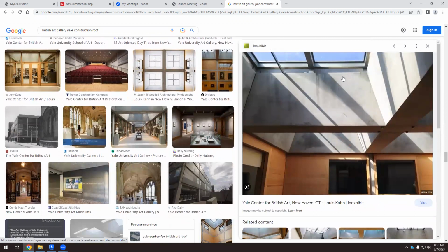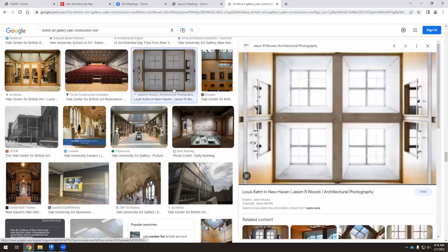So the goal is that we have a roof, it's a pyramid, we have a skylight, and this is exposed concrete. Well, we are going to add better quality to this detail. So we will try to provide this pyramid with thermal insulation. In the original state, probably it doesn't have thermal insulation. It's a prefabricated concrete wall, and it's placed there, and that's it. I told you that this was made in the, so that's a picture, again, looking from below. And this is what it looks like.